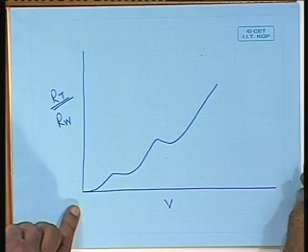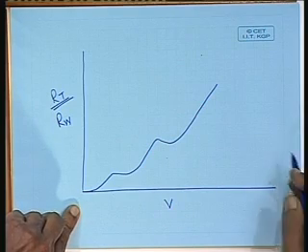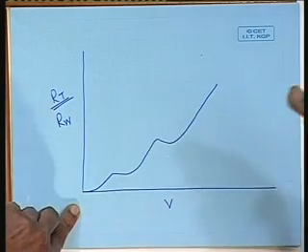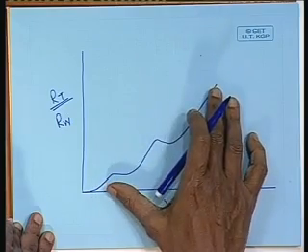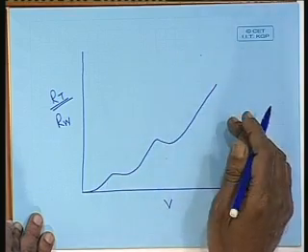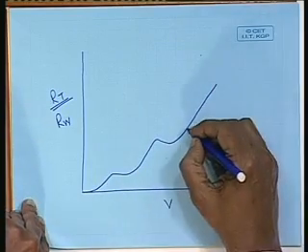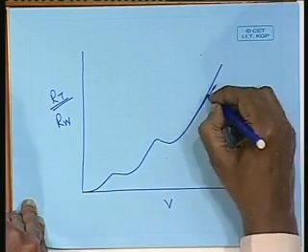this will go on till about 0.4 Froude number. If I go on increasing the speed, it will go on to about 0.4 Froude number, after which the vessel will generate sinkage, it will sink to a larger depth, and then some other phenomenon will occur. We will discuss that later. But for displacement ships, Froude number is normally of the order of 0.2 to 0.3, within which the characteristics will be like this. Now, if I am plotting this, this power will be the sixth power.